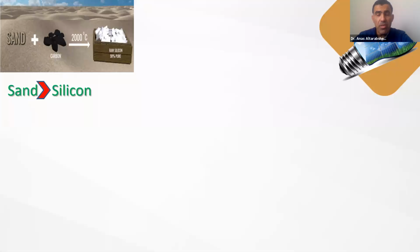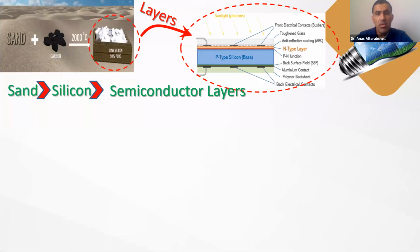We have to purify it more and more with extra chemical reactions to get a semiconductor layer. Now, the semiconductor layers could be either intrinsic, that means pure silicon, or they could be extrinsic. The extrinsic could be p-type, that means we add some boron atoms, or it could be n-type, that means we add some phosphorus atoms. Those atoms are added to enhance the performance and the conductivity of the silicon materials.